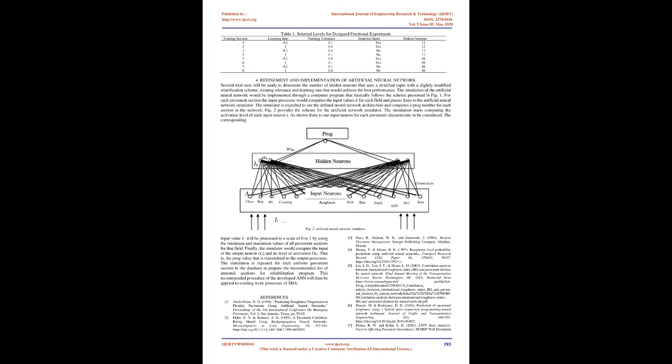Homogeneous sections will be delimited by using past and programmed project information, and the averages for all of the parameters considered will be computed and recorded for all sections longer than 5 miles. The neural network will then be trained, ensuring the number of non-programmed sections are similar to the number of programmed sections. Step 3. Ensuring good performance of network.